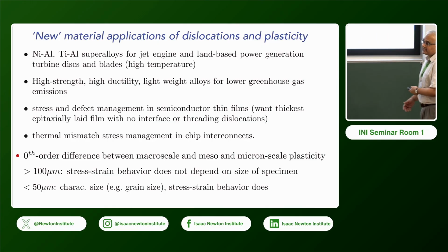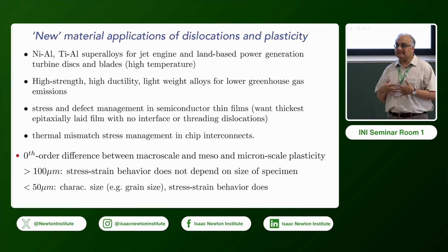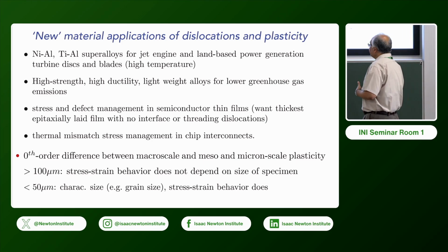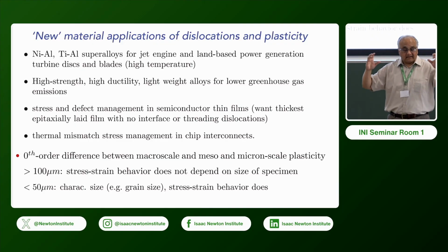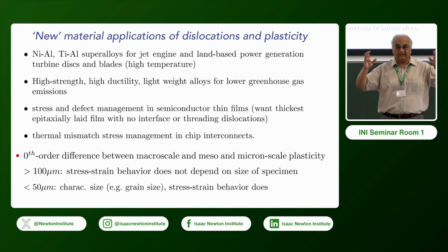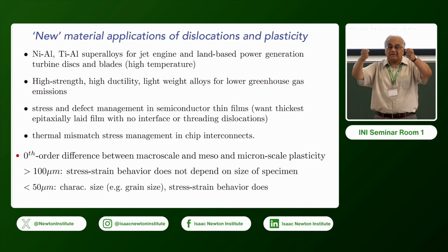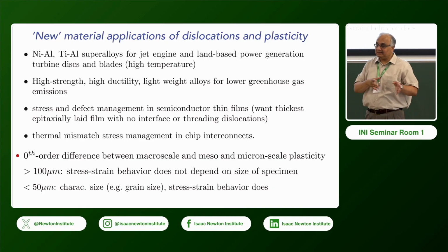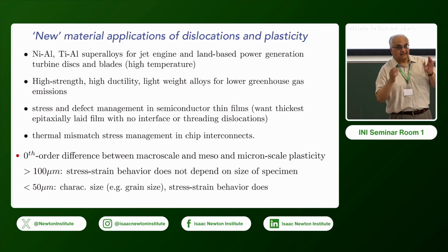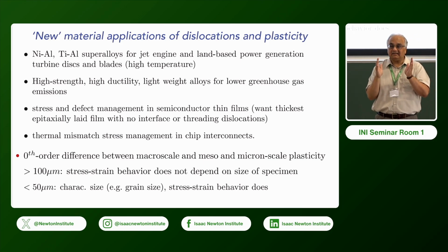So one of the things that happens in terms of modeling, the difference between macroscopic plasticity and microscopic, is the following, zeroth order. Forget about patterns and all that. At macro scales, you do a stress-strain behavior for a material. You take one, you pull it, and the basic output from an experiment is force displacement. But for the same material, people who do solid mechanics learn this as a sophomore or freshman: force displacement is not a material characteristic, okay?